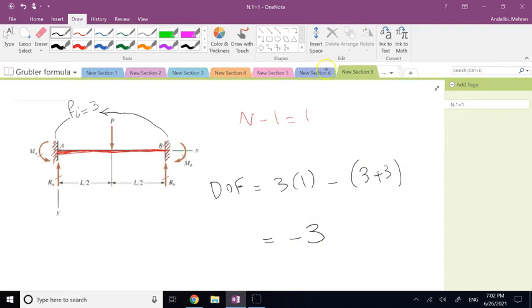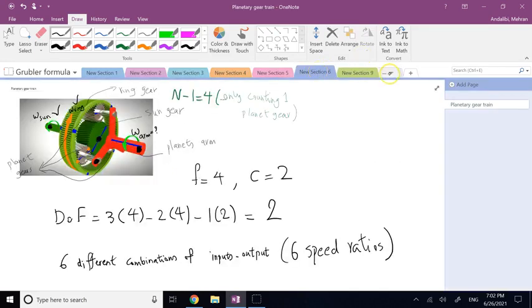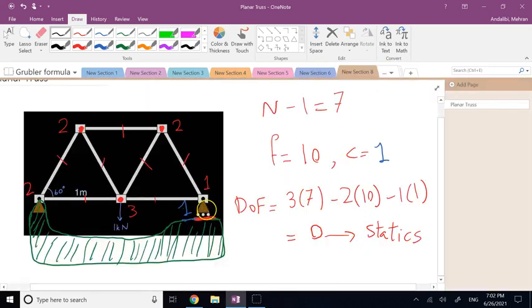The same thing could have happened here if instead of having a roller here, you also pinned down this side. So instead of a pivot and a roller, if you made it a pivot and a pivot. So did not allow the right side to go horizontally, only a pure rotation.